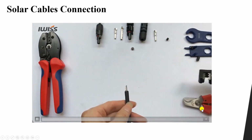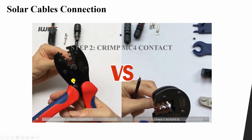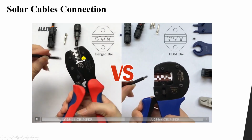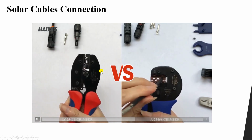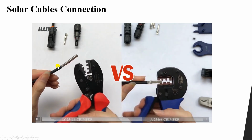Okay, now what is the next step? The next step is that I'm going to add the contact. You can see here two types of contacts depending on the crimp of the MC4 connector. Okay, so you can see we added first the contact, then we are going to add the cable like this. Okay, then we will compress like this. So you'll see what will happen in this case. You will find that the cable and the connector became one part.